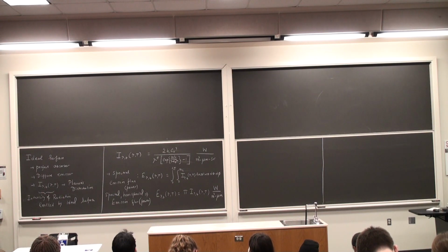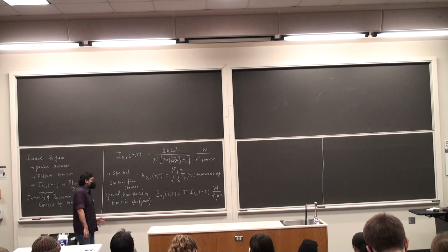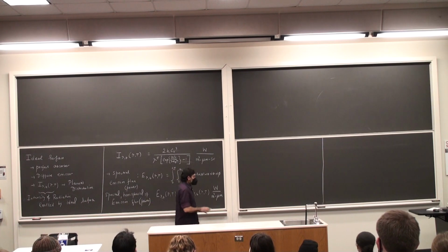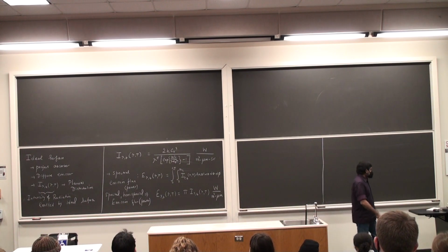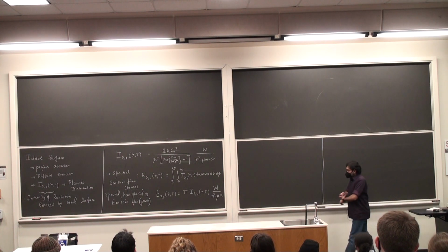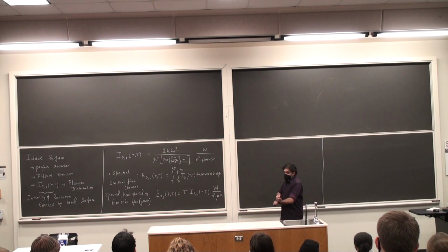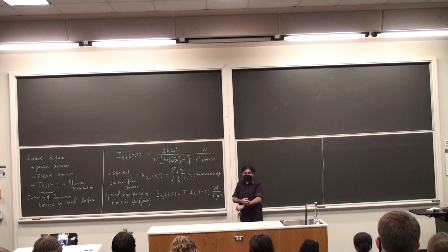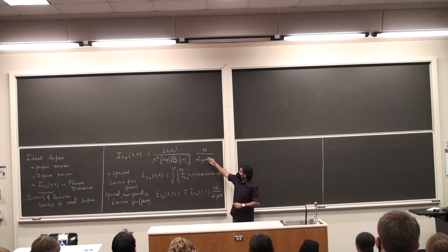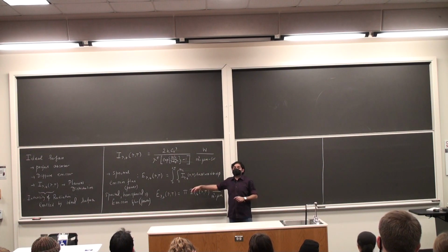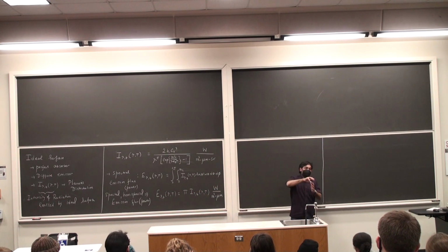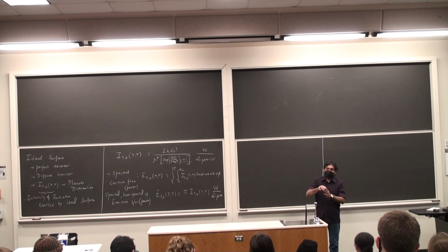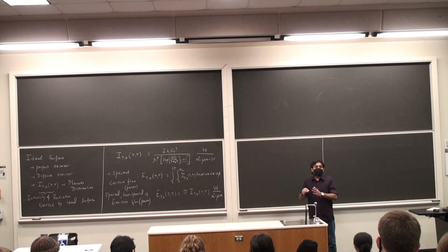So what we have found out is that there is this ideal surface which is more or less well understood based upon fundamental physics, quantum mechanics, and also we have some nice formulas that enable us to calculate the intensity if we so wish, or the spectral emissive flux if we so wish, or I could take the spectral emissive flux, integrate it over the entire wavelength range, and I'll get the total emissive power or the total emissive flux.